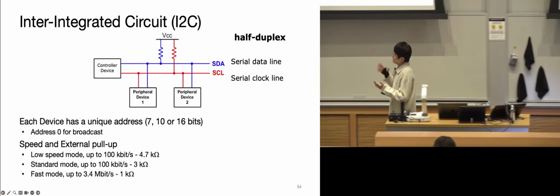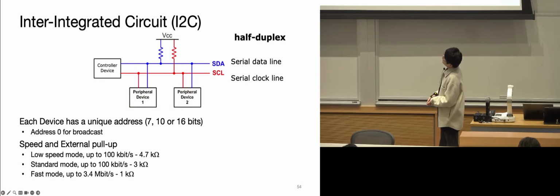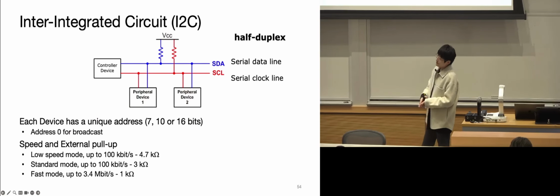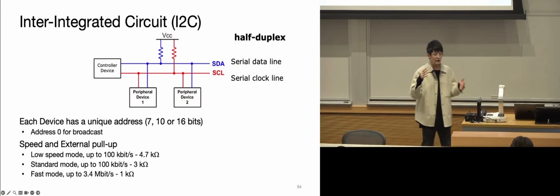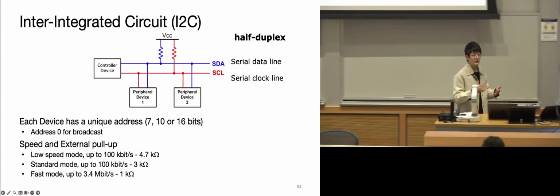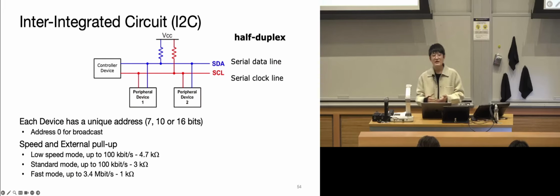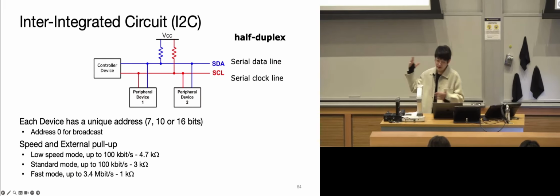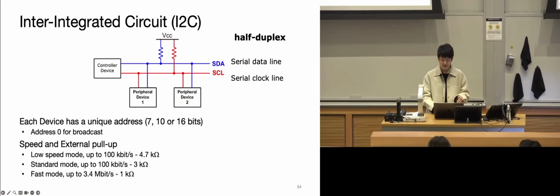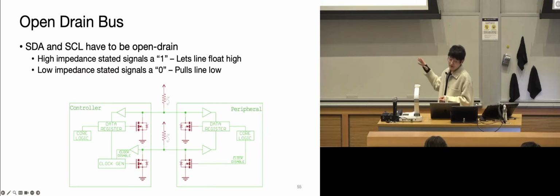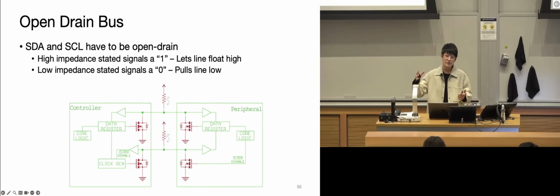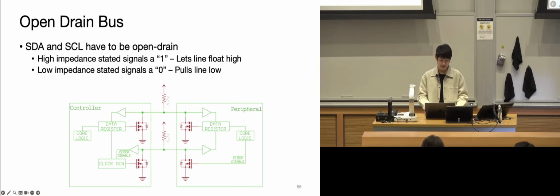So if you have a signal that's pulled up or pulled down too fast or too slow, usually too slow is the issue, it likely has something to do with the resistor values. And both of them are implemented, like we just said, as open drain, and then you need to put a pull-up resistor on that.